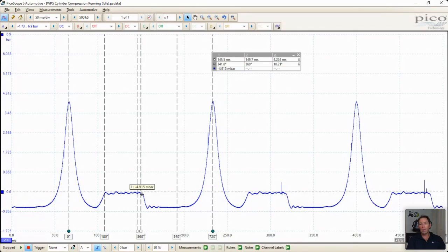And that'll tell me whether my cam chain or cam belt's stretched by using these measurements. So this particular vehicle maybe is supposed to have an intake valve opening at 25 degrees before top dead center. Well, if I have a look at any engine that has a stretched cam chain or stretched cam belt, everything will happen later in the cycle because it's delayed. And what that means is the valve will open later in the stroke, which means it'll open closer to top dead center, which means my valve opening point will be less than what it's supposed to.